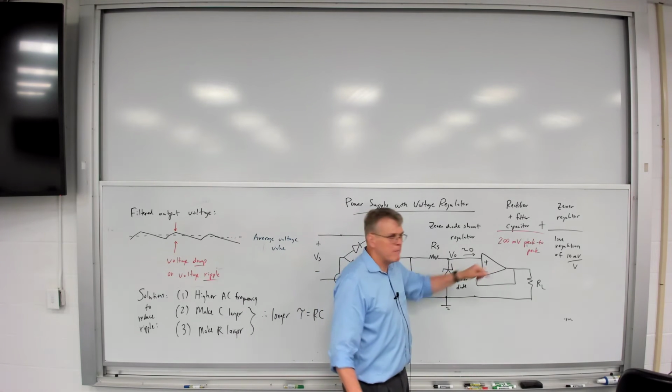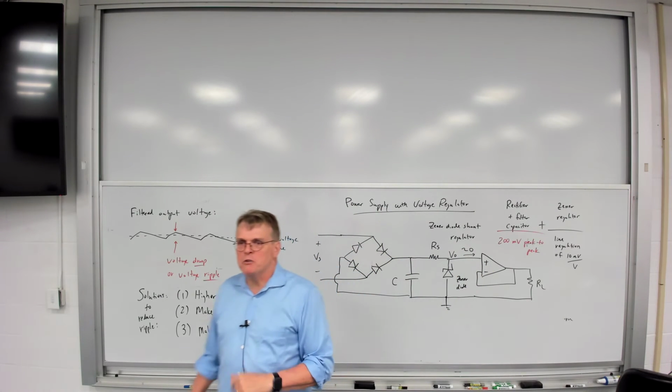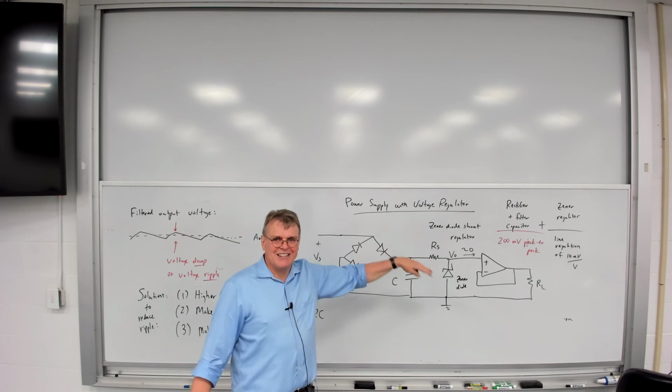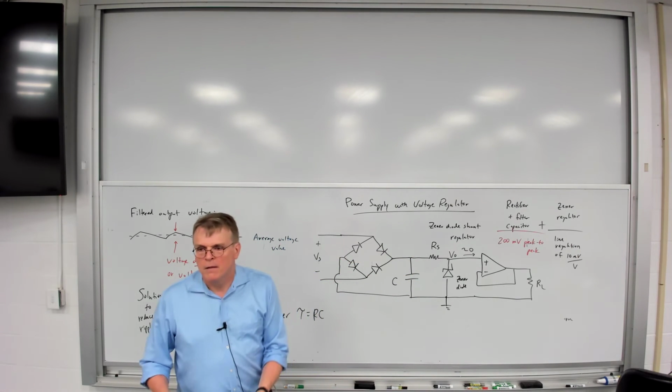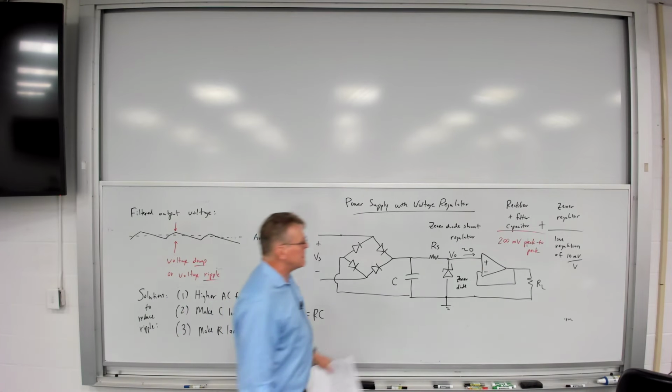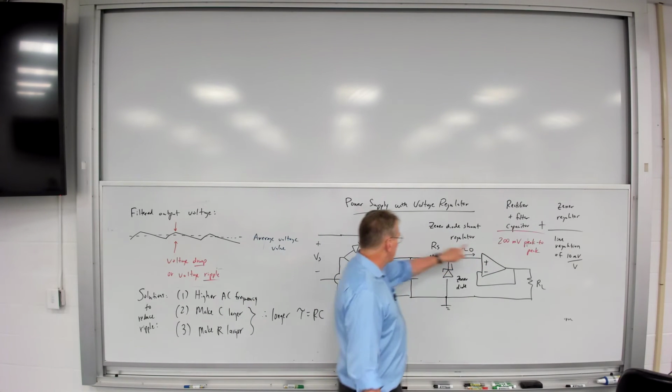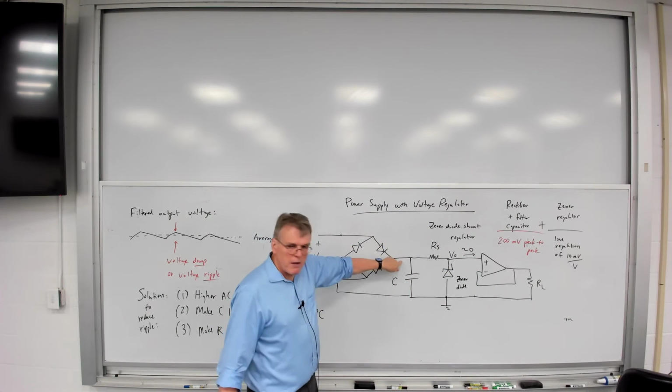Not perfectly. No op amp is perfect. But it's going to drop something perhaps in the millivolts down into the microvolts. Yeah? How do you power the op amp? Well, the op amp typically is going to be powered generally by the same voltage you have back here.